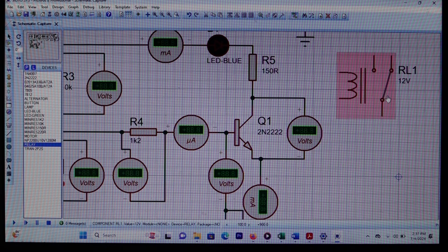That equation states that VCC, the voltage across the collector, which is 5 volt for our case, is equal to collector current times collector resistor plus the voltage across collector emitter, which in short we call VCE. Right? We have taught you to write dictation. So this is simulation with engineering dictation. Then, that is the mathematical equation.